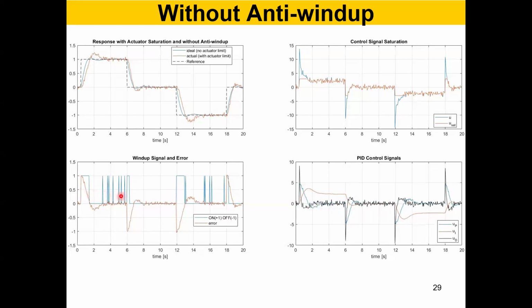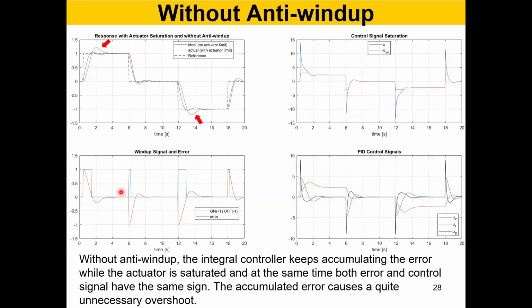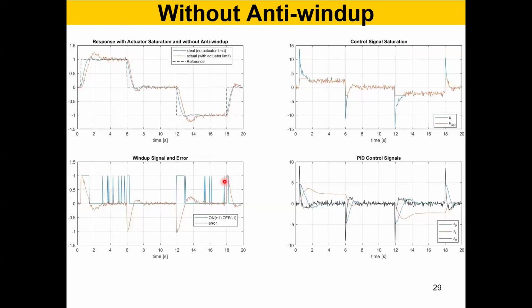Therefore, on many occasions the control signal demand goes beyond the limits. So you can see here and there, anti-windup kicks in here, here, and this is basically because of the noise. Quite unnecessary. Okay. Now, actual anti-windup is only in these 4 places. But because of noise, you have a lot of anti-windup kicks in here and there, quite unnecessary. And this is what noise can do to a system.